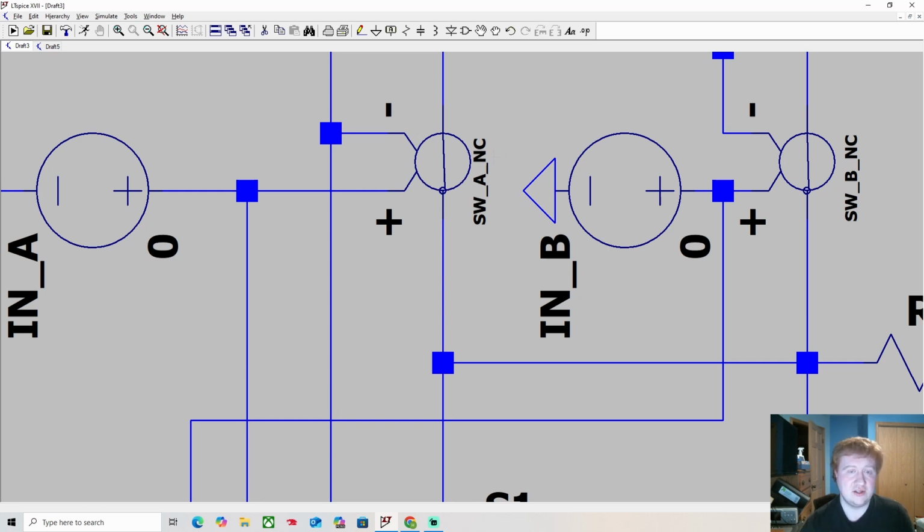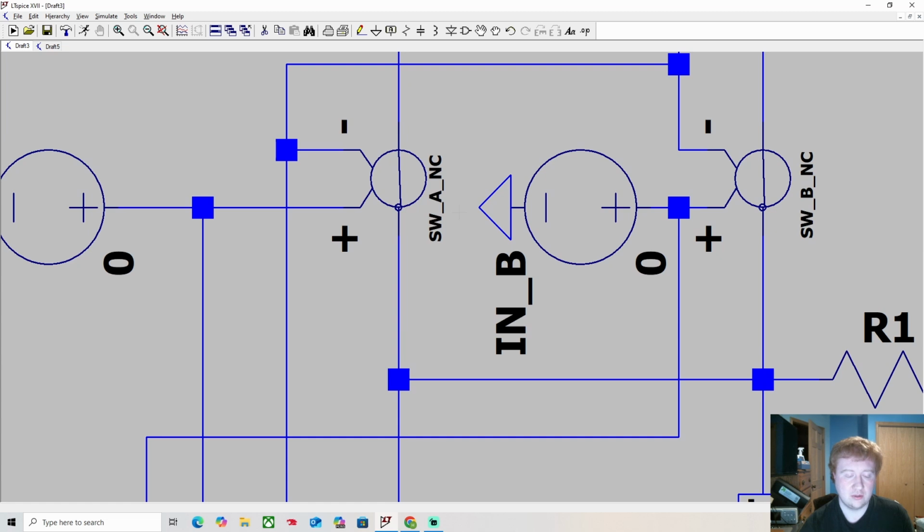All that I need to make clear is the difference between a normally closed and normally open switch for those that aren't familiar. Imagine you've got a clicky switch in your hands. If you didn't press it, a normally closed switch means that it would already have continuity between the switch part. So that means that from point A to point B, there's already a connection in place.